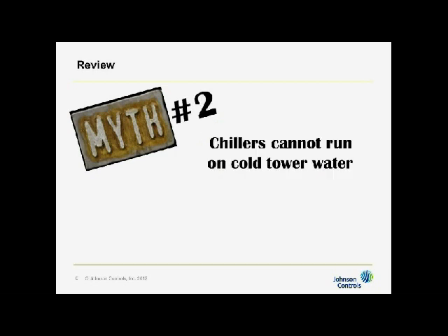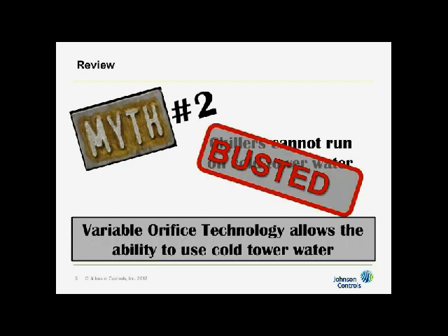Myth number 2 was that chillers cannot run on cold tower water. That one was busted because if your chiller is designed to be able to handle oil eduction to get oil back to the sump, if your chiller is designed to be able to handle heavy loads or full load with minimum condenser water, that's usually done with a variable orifice, then you can definitely handle low tower water and not only save energy but operate consistently and stably.